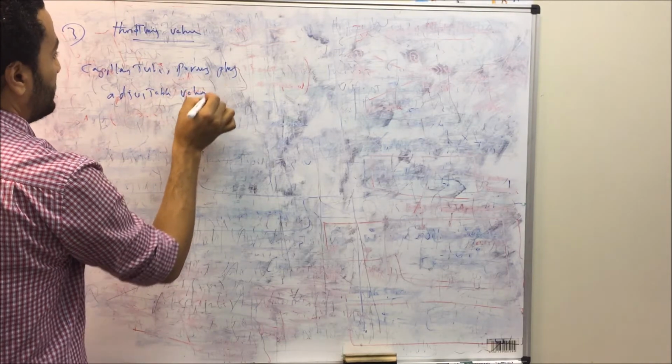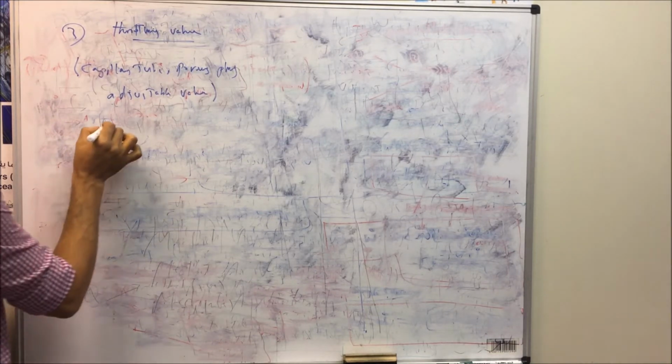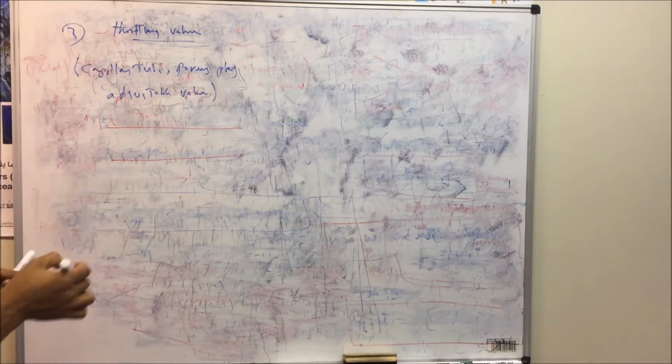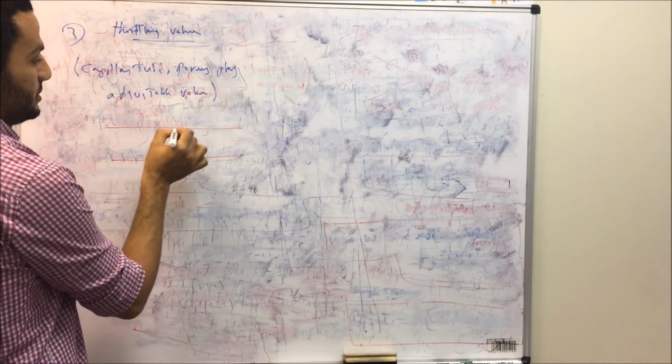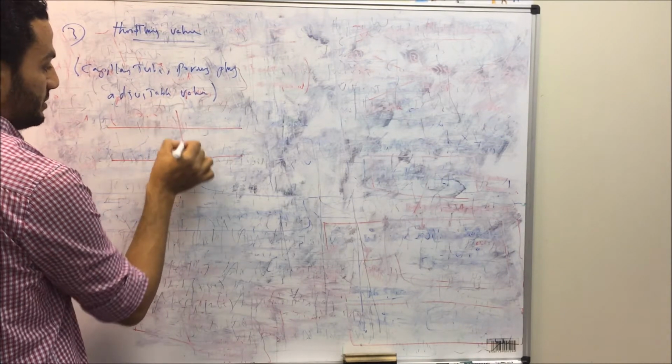All of this means we have the case of a throttling valve. The idea of the throttling valve is that the flow goes through a very small area, so we have a high amount of pressure losses within the system. So the pressure will be reduced, and also the temperature will be reduced.